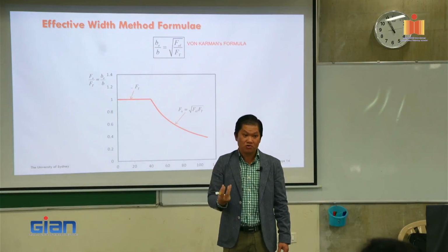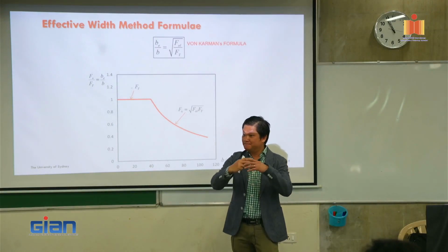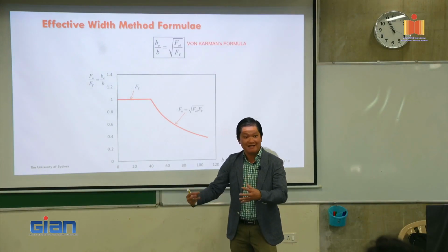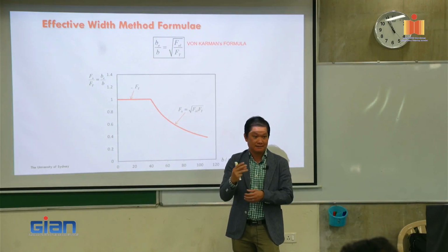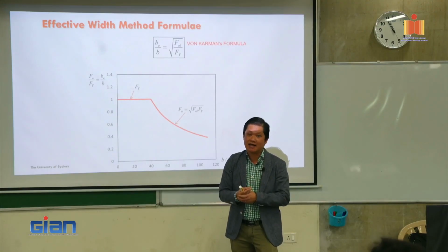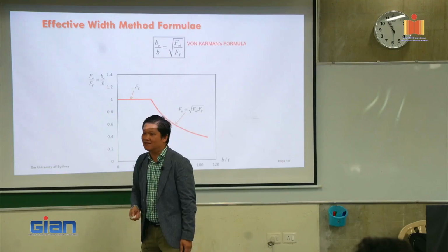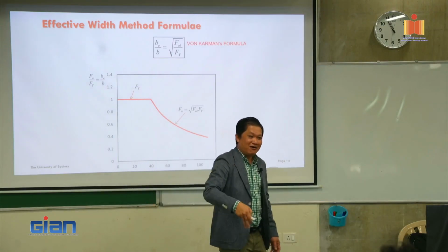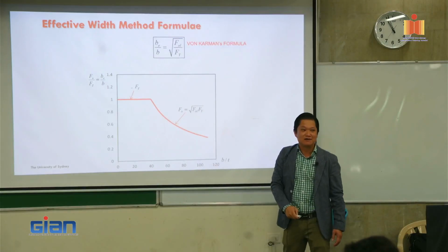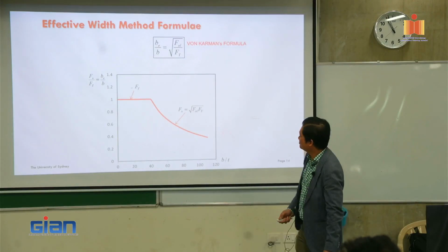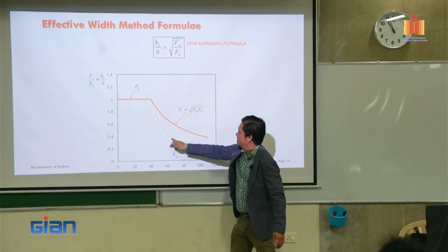Because of the heat when producing hot roll steel, and when it's cooling, it creates residual stress in the member. So we need to take the effects of that into account. So the standard says we need to factor down a little bit, because using that is a little bit unconservative.